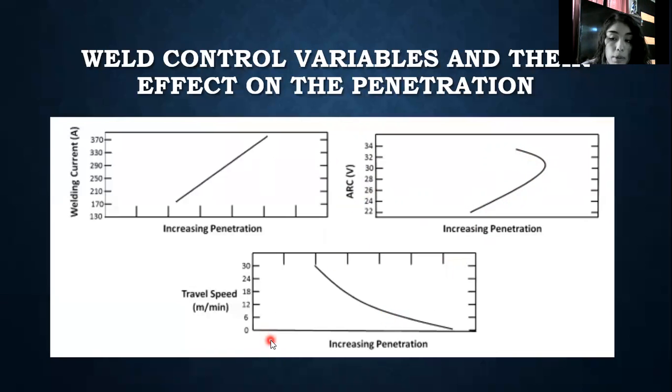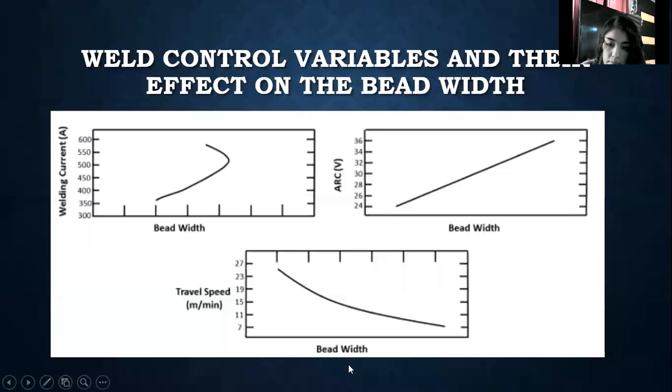And the travel speed: if the travel speed increases, the penetration decreases.